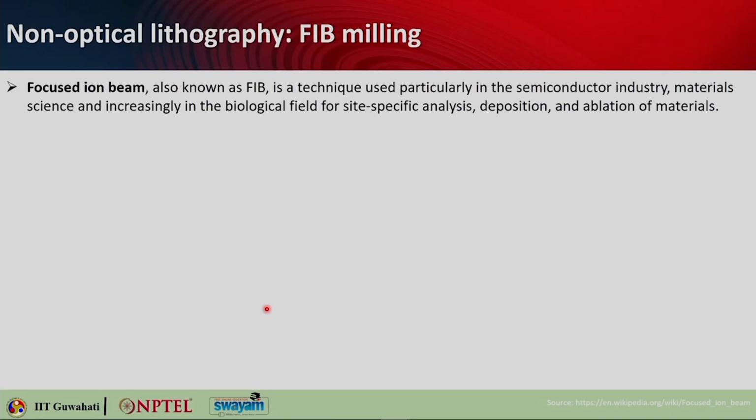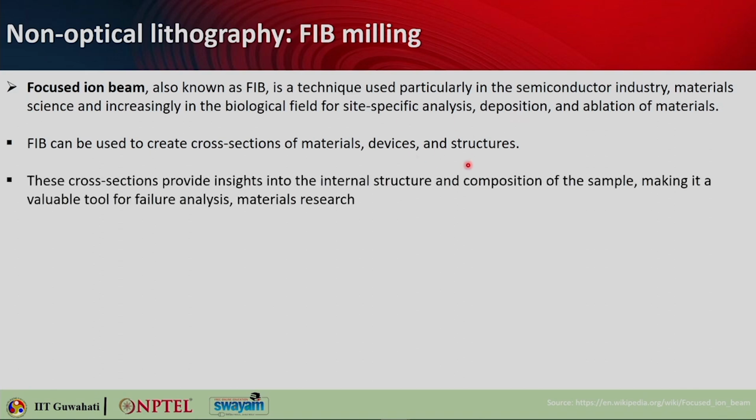Another non-optical lithography technique is FIB, that is focused ion beam lithography. This is a technique which is used particularly in the semiconductor industry and material science, and it is also getting increasingly popular in biological fields for doing site specific analysis, deposition or ablation of materials. Focused ion beams can be used to create cross sections of materials, devices and structures.